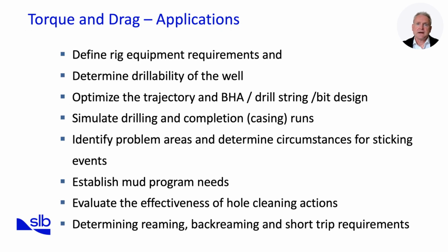Analyzing torque and drag has a wide range of applications, and this slide outlines the most important ones. First, we use it to define rig equipment requirements. By predicting torque and drag, we can determine whether the rig has sufficient hook load, rotary torque capacity, and top drive performance to safely reach the planned depth.